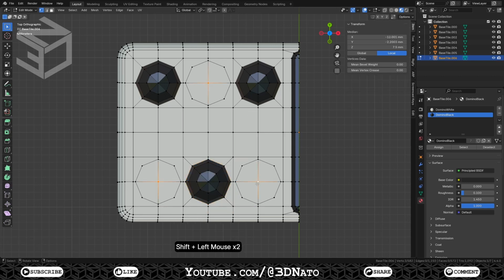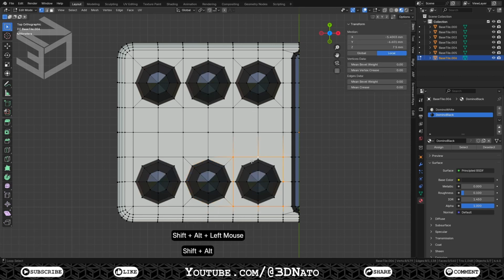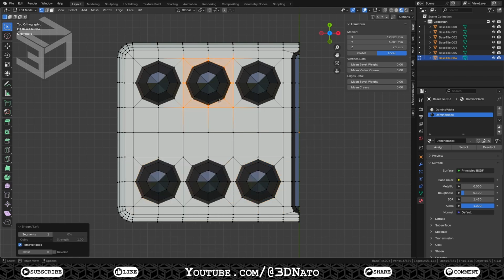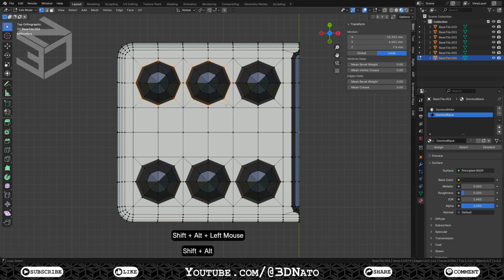Now it's just a process of repeating the same steps on the remaining 3 dots. After you finish creating the faces, let's create some edge loops so they are sharp after the subdivision surface modifier. Select all edge loops around the black material, press Shift+E to crease, type 1, and enter to confirm.